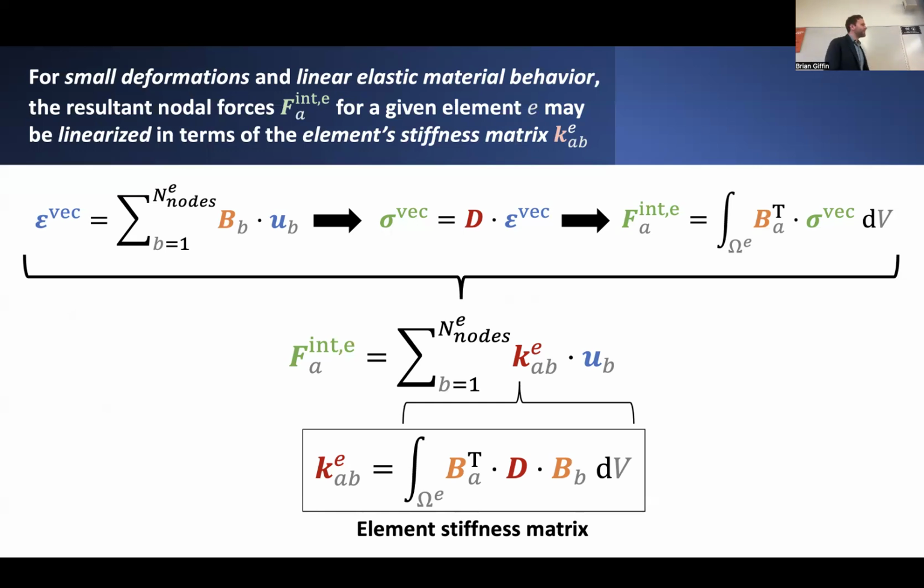So it's not so different from what we were looking at in one dimension. It's just that now the resulting entries of the stiffness matrix, or rather sub-matrices, are potentially themselves small arrays. So for example, this particular sub-matrix entry K_AB is itself a small 3x3 matrix in the case of a three-dimensional problem, or a 2x2 matrix in a two-dimensional problem.